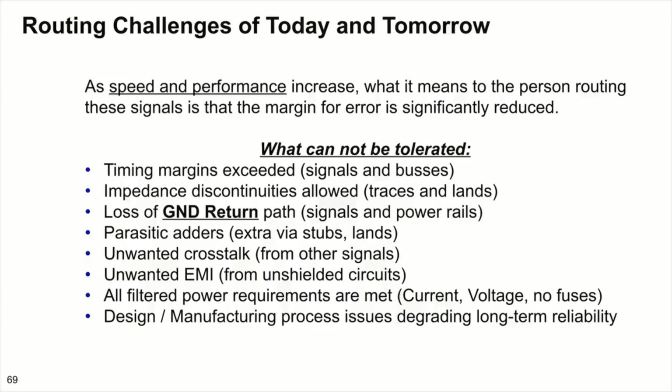So considering some of the challenges of our circuits today and tomorrow, we'd looked at this before as speed and performance increase. There are certain things that it's going to mean to that person routing these signals. The margin for error is significantly reduced. What cannot be tolerated with today's circuit is that our timing margins cannot be exceeded. This is for signals and buses. There's a certain amount of length based on the rise time